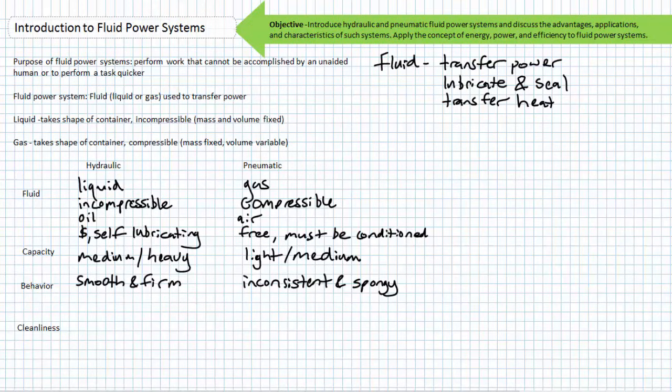This, in my personal opinion, is the principal advantage of hydraulic systems in comparison to all other systems, be they electrical, mechanical, or pneumatic. Hydraulic systems, in addition to being capable of lifting large loads, have incredible holding power. Liquid, being incompressible in nature, means that once pressurized flow enters a cylinder and lifts an applied load, any fluid trapped inside that cylinder may as well be replaced with a solid object if it is not allowed to leave the cylinder.